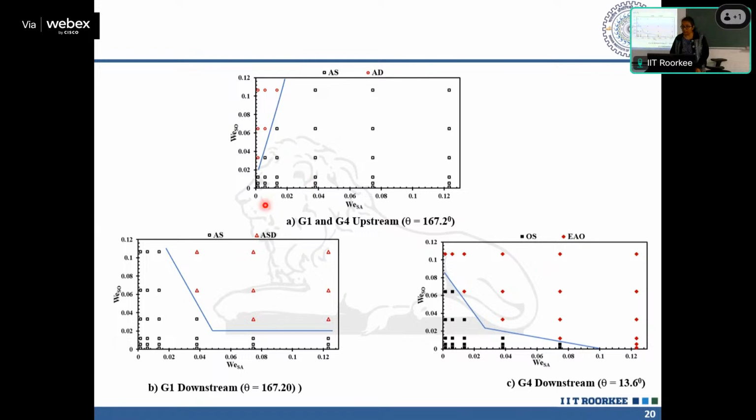Only a change in the area gives you the same type of flow regime with some change in shape or formation of additional drops. When you combine it with a change in contact angle also, you will end up with almost a new flow regime map, with the dominating flow regime being some other type. Okay, encapsulation we haven't seen till yet. So this is the result of sudden change in wettability.